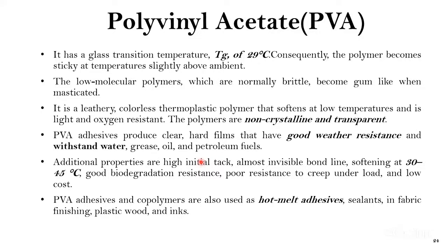Say this is amorphous, but the amorphous percentage out of 100 is 40%. If 60% is crystalline, then you can see it is translucent. It depends upon the percentage of amorphous character they carry. If any material is 60% amorphous, then the remaining 40% is crystalline, and in that case we call it semi-crystalline.